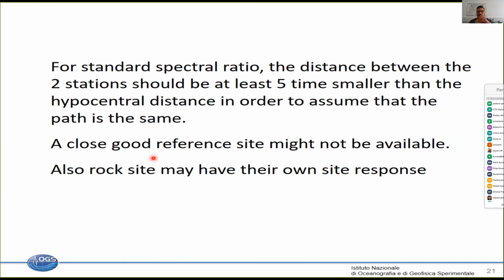The other important point is that this method can only be used if there is a good reference site nearby the site where I want to study site amplification. In many cases it can also happen that I don't have a rock site, or a very good rock site, close to the area where I want to study this.